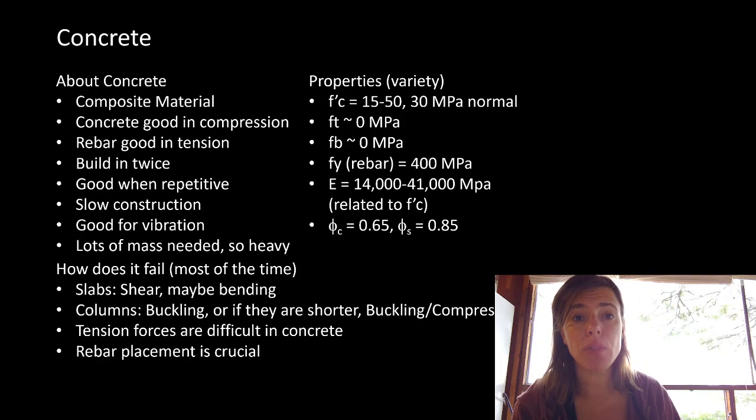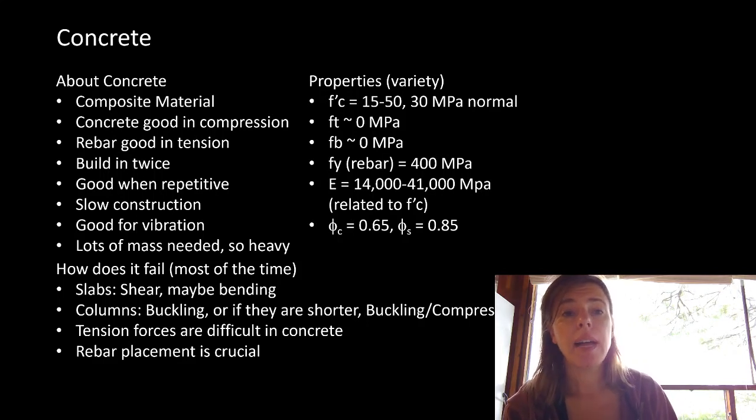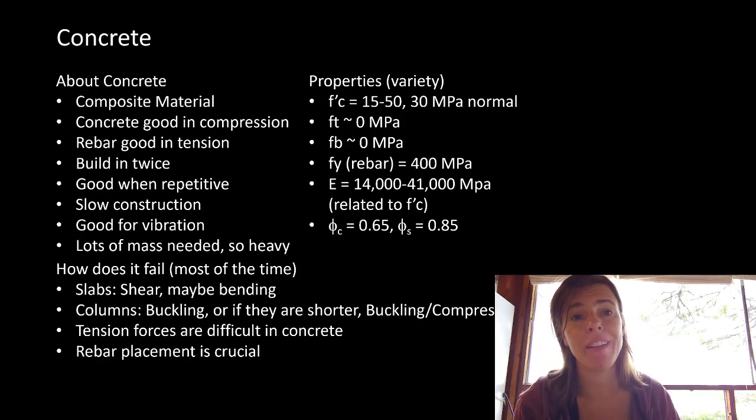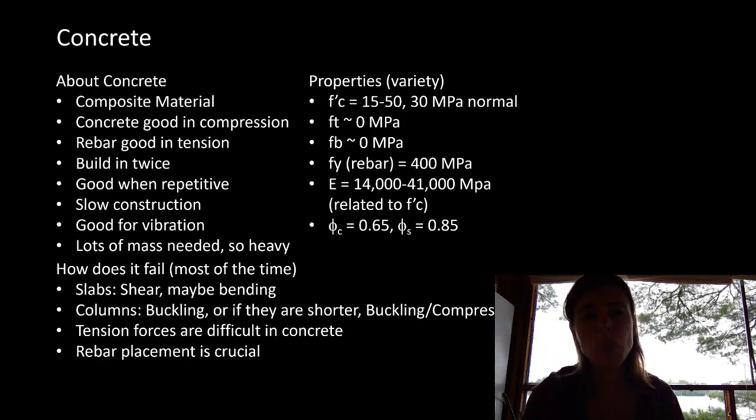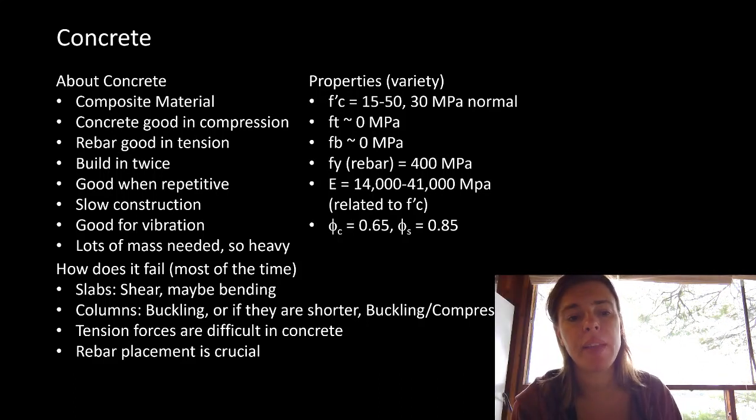It's really slow construction because we have to wait for it to cure. That building below has to be strong enough to hold the parts above it. So we can't build the next floors until that concrete has cured enough. Concrete's pretty good with vibration because it's so massive. It's massive enough that it can dampen a lot of our vibration loads, which we're going to see has some impact on certain things. But it's also very heavy. Its own self-weight can start to be a bit of a problem. And so that can be a limiting factor in building with concrete.